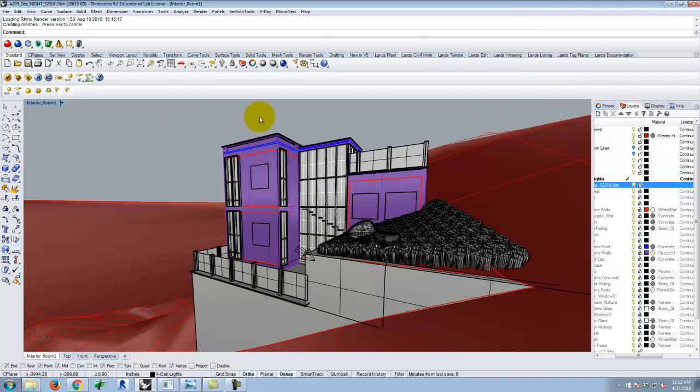But if you use something else, you want to make sure that you go back to your original block, edit it, and change the material to be just a very basic glass. We still may need to do some adjustments to get a little bit more light spilling out of the windows, and I'll show you how we can go about doing that should we need to do it.